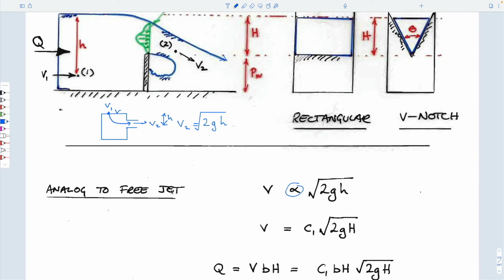So what we need to look at is what would be convenient to measure here. We've put this across the stream. It might also be a weir on the Allegheny River, which is a permanent weir, which is running all the time. And if that is, then this is a concrete obstruction, and we would have a gauge at the side to measure the flood stage or the water level, and that would give us directly the flow rate of the river in cubic meters per second or cubic feet per second. And of course, that's how they do it.